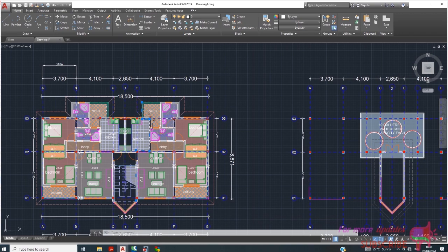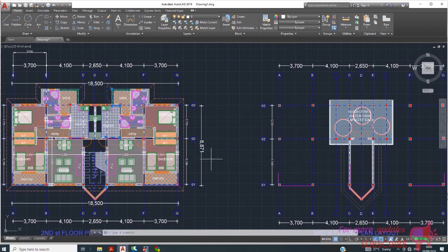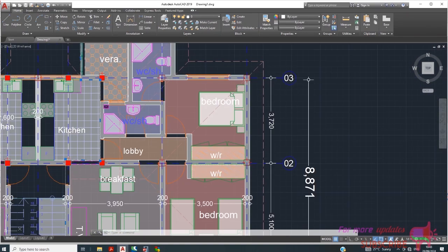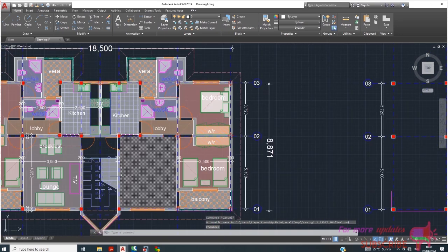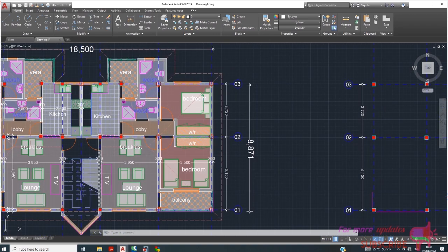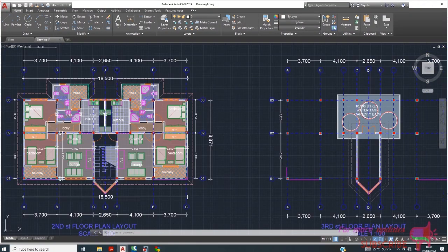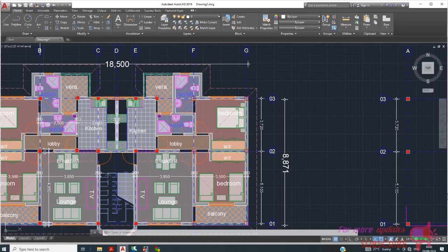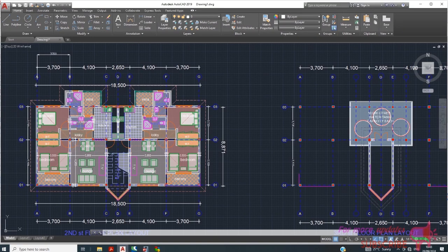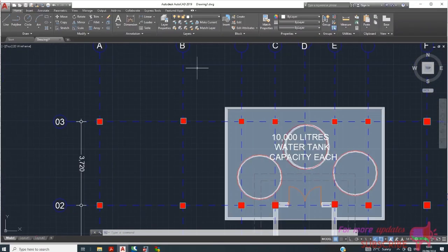the other side, right? So we can model this building up to this point, and then we are going to mirror the design of this side to this side. Only don't forget that these columns and these beams have to be similar to this and these columns also. So this beam is not at the edge, or rather it's also supporting this slab here. So don't forget that when you're mirroring the design. So you're also going to mirror the design of these columns and these beams here, and the rest you can just mirror because these columns are also at the edge.